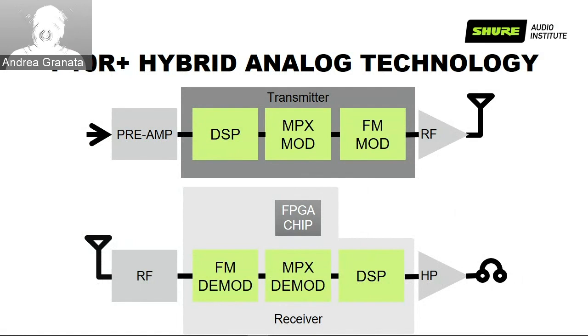And I'd say also, if you set up, let's say, a PSM 1000 in mono, at the receiver level, what happens is that it's broadcasting on both sides of a multiplex mono signal, then goes back and sums up left plus left or signal A plus signal A to boost the usual 3 dB in signal to noise ratio, but you don't have additional power or, as far as I'm concerned, any other benefit using in-ear monitors in mono versus stereo.